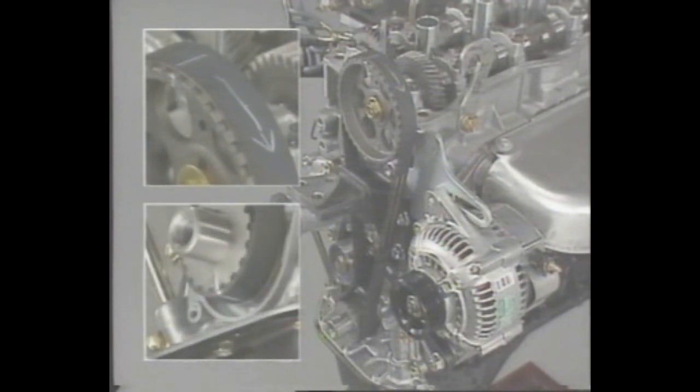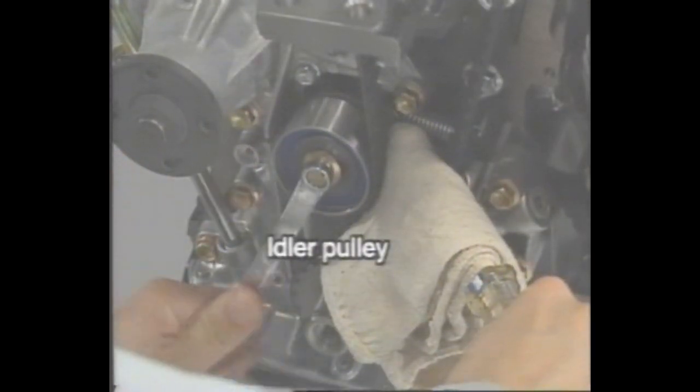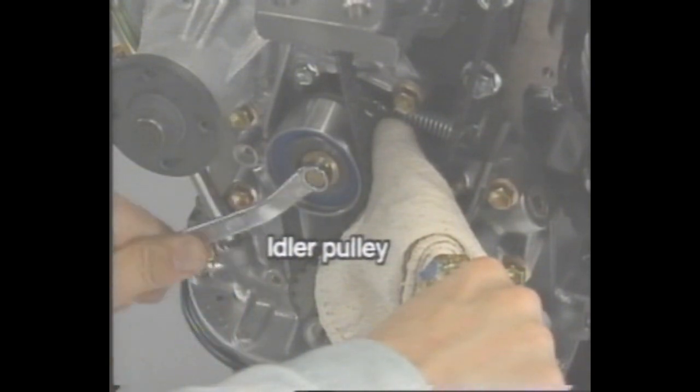At this time, with chalk or a similar marker, draw an arrow showing the rotating direction on the rear side of the timing belt and idler pulley. This enables keeping the same fit of the timing belt. Loosen the idler pulley bolt. Loosen the timing belt and temporarily tighten the bolt. Then remove the timing belt and idler pulley.